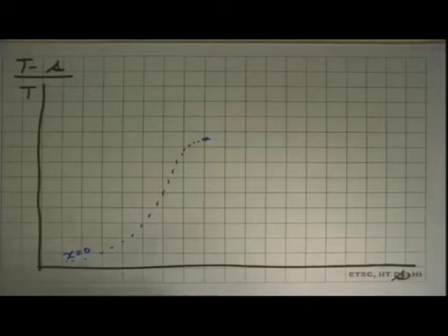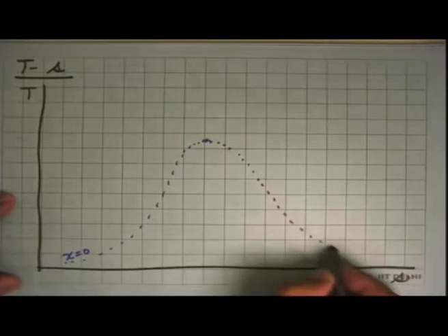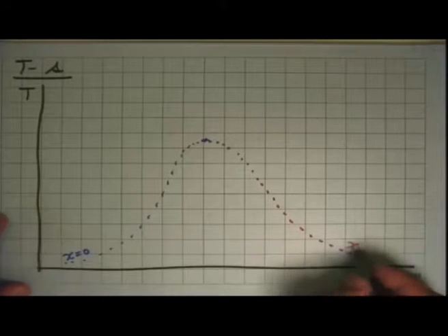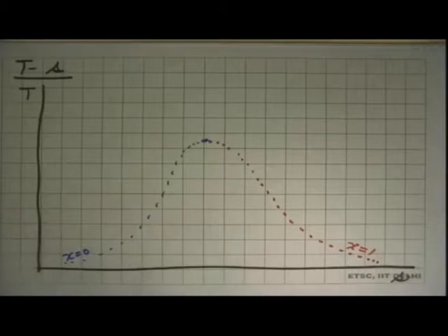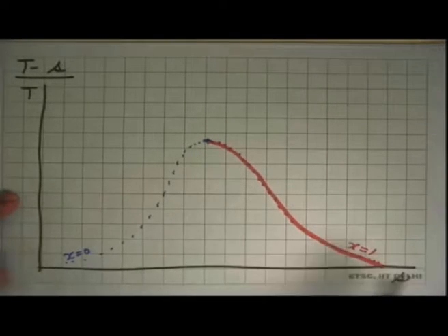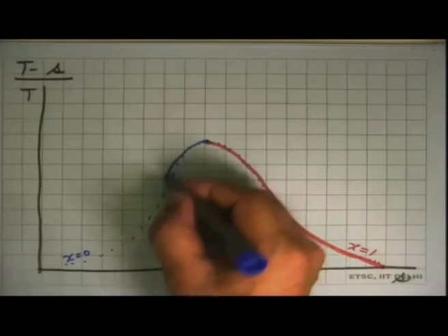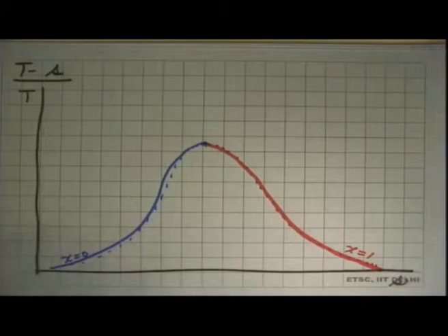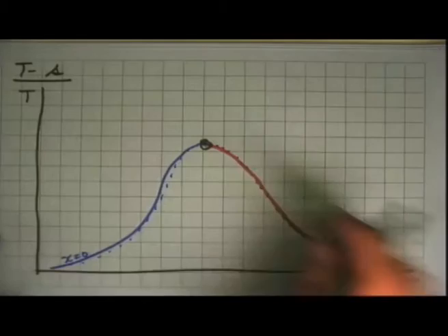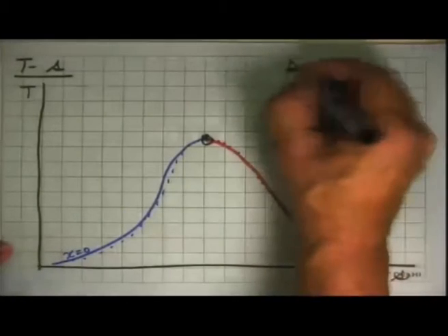And we continue the same plot. We take all the properties of the dry saturated vapor and make a plot, and it looks something like that. This is all x equal to 1, and we can join all of these. This is the saturated liquid line, and this side we get the saturated vapor line, and at the top is the critical point. So this is the dome.